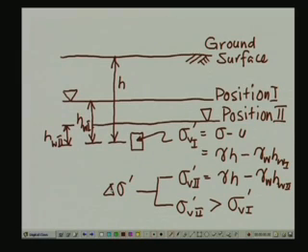So, the compression of the soil layers such as those shown by the element on this particular cross sectional sketch is going to be quite uneven, and as a result you are going to have uneven settlement or uneven vertical sinking of the ground surface within different parts of the zone that is going to be affected by permanent lowering of water table.